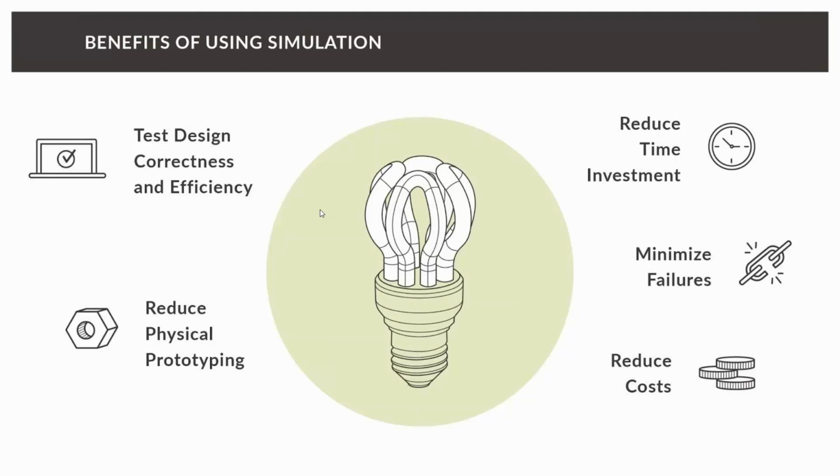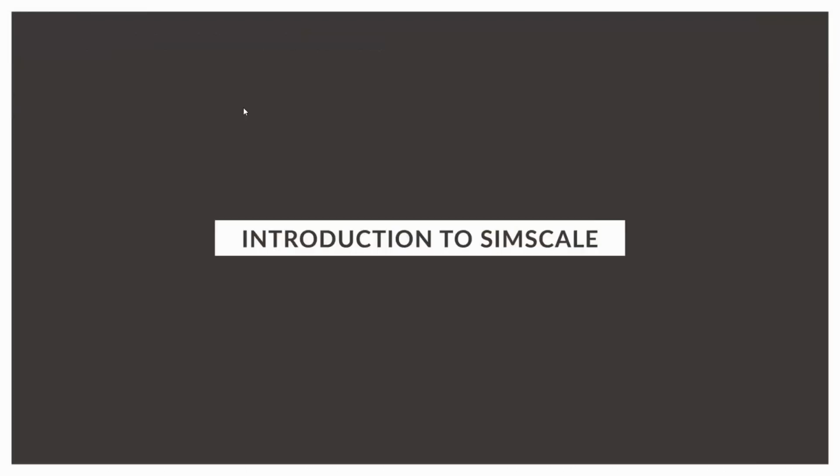A workflow which is used in motorsport is, for example, that you want to design a new front wing. First of all, you simulate the profiles and find out, of 50 profiles, which 10 profiles are working the best. For these 10 profiles, you do 3D CFD of the full car with the wing, and then the 3 best design ideas are tested in the wind tunnel.